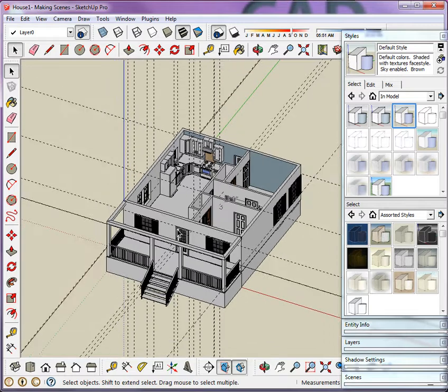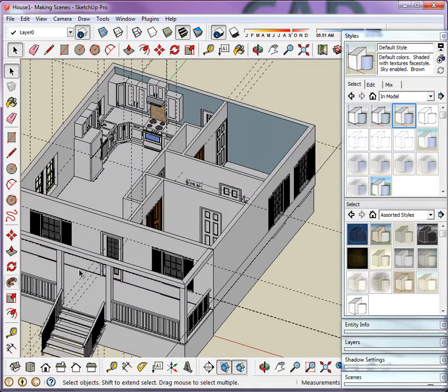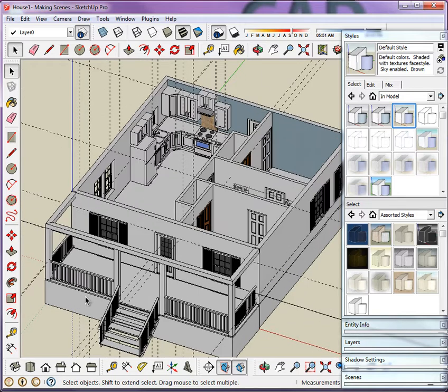So, a floor plan is really a horizontal section through the entire building, and it's usually about 36 to 42 inches above the finished floor plane. So, what I would recommend anytime you want to do a parallel or perspective plan view, use a section. Let's use section plane here.